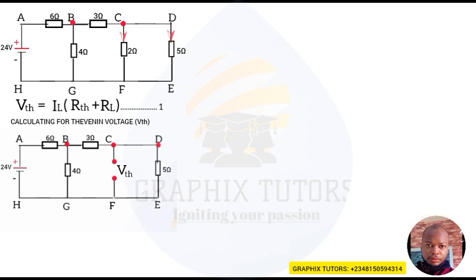That means the current going through part CF will not be the same current going through part CD. Because of that, we say these two parts are in parallel. That is, part CF and part CD are in parallel. And we know in a parallel network, the voltages are the same.